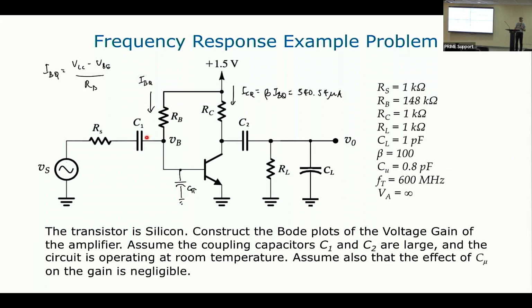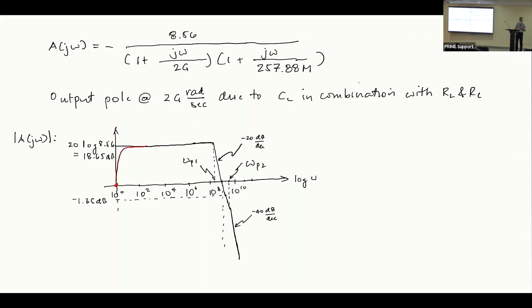And this gain, no, we actually refer to this, may term tayo rito, we refer to this as the mid-band gain. No? Because most of the time we will be operating here. No? In other words, we want our amplifier, for example, to have a constant gain between a certain frequency and a certain frequency. So we design our amplifier that way. We design the location of our poles and zeros so that we achieve a certain what we call mid-band gain. No, usually we don't operate it here in this region because babagsak na yung gain natin.